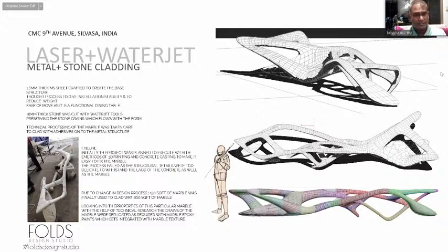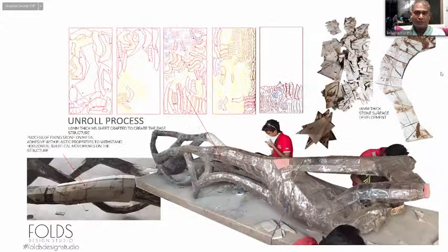It was not easy at all, but finally we achieved what we wanted to. So you can see we used metal frames again out here. We cut metal and then joined this. Instead of having a reinforcement inside, we used this metal tubular structure which was completely welded as per the design. Then we cladded the Italian marble on top of this.